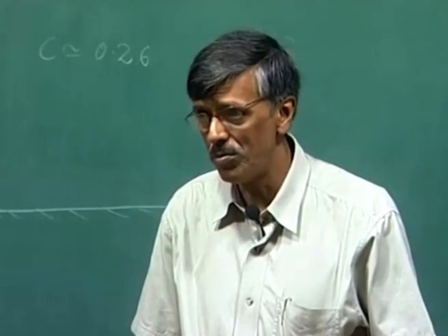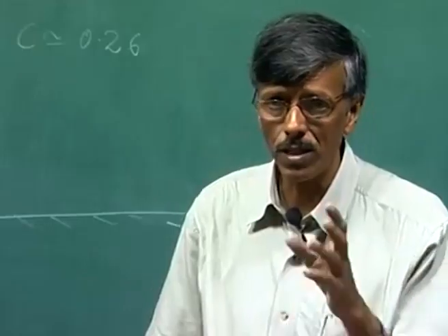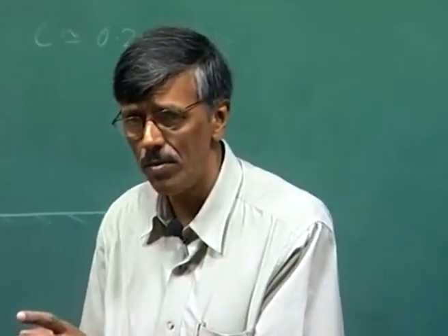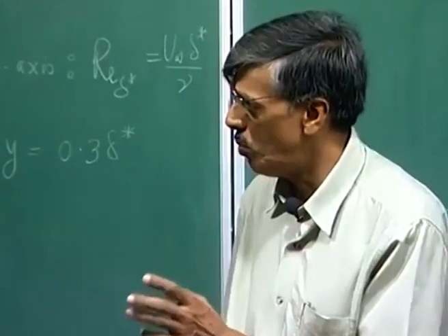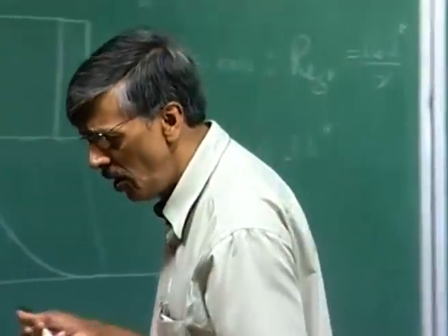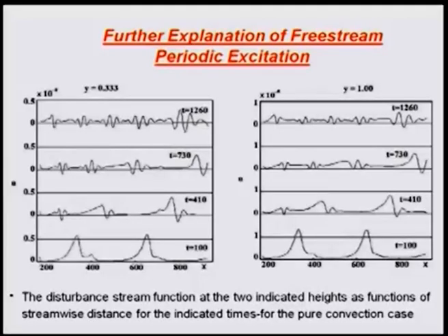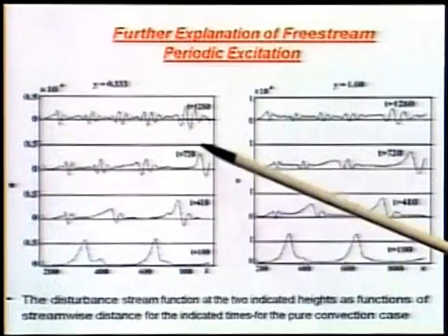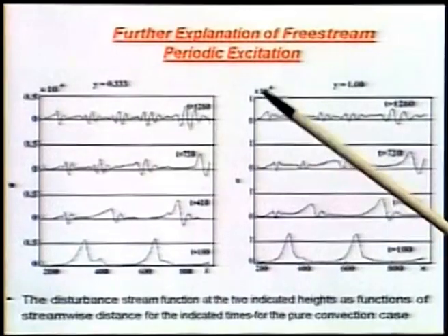That we have done the eigenvalue analysis, and we have seen that if we create a particular length scale and a particular time scale, then we can create TS waves. So, what we are saying is that even though you allow an inviscid vortex to go to begin with, it will be pretty harmless, but with the progress in time, you are going to see that it is going to fill up all kinds of length scales. You can take this solution and do an FFT, and you will see that it is quite a wide band phenomenon. The question is about the corresponding omega naught.